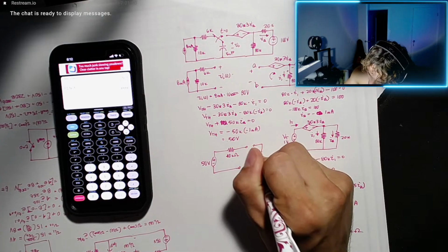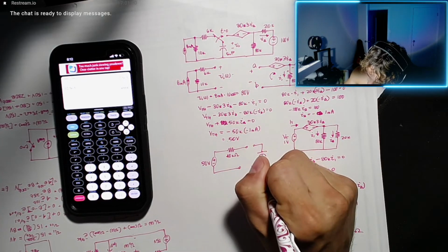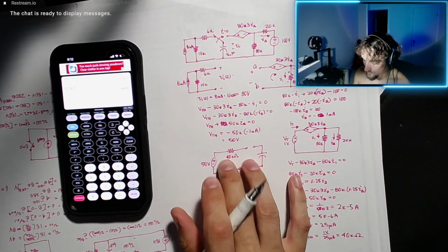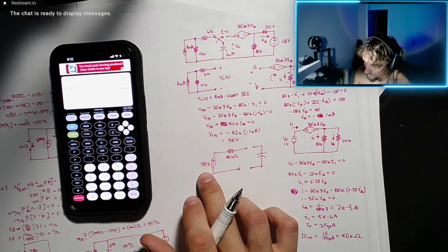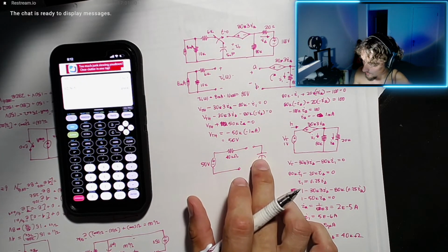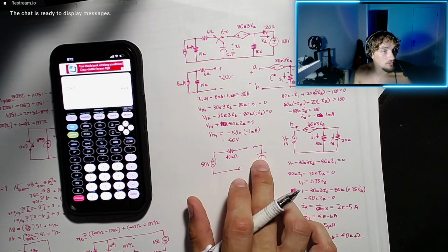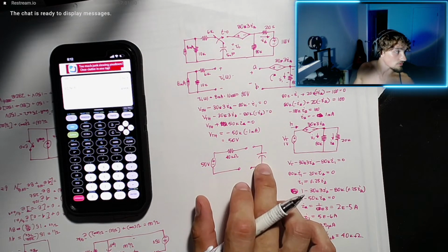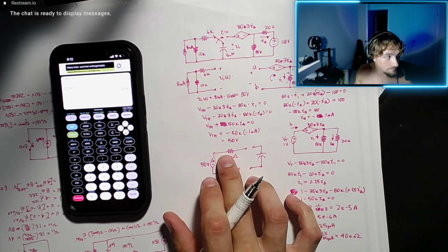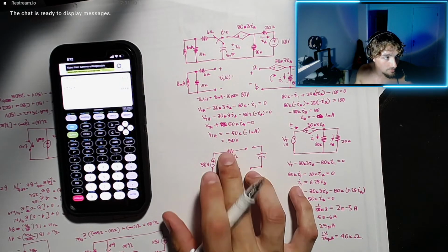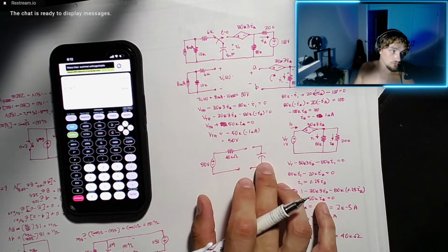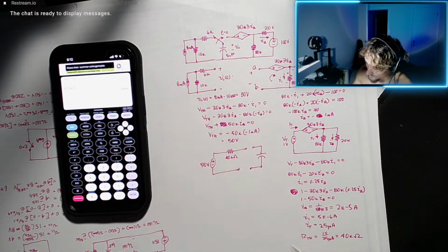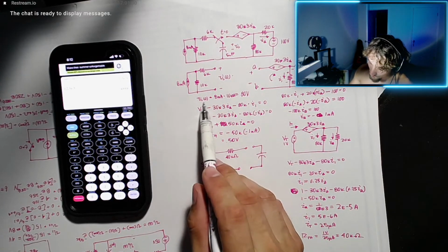And then we'll attach the capacitor. So this will determine our RC, and then we have our final voltage. In our DC analysis, as t goes to infinity, the capacitor will look like an open circuit, and therefore no current will flow. There will be no voltage drop across this resistor, and the capacitor voltage will just assume 50 volts. Okay, so anyways, VC naught equals 80.